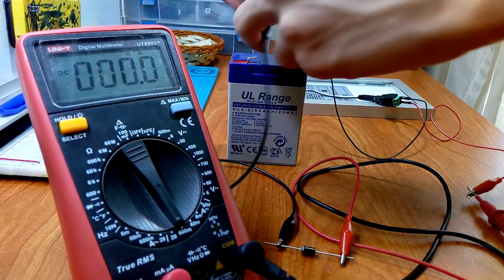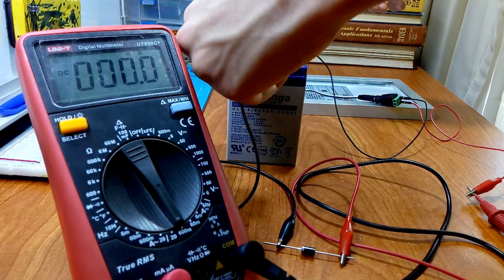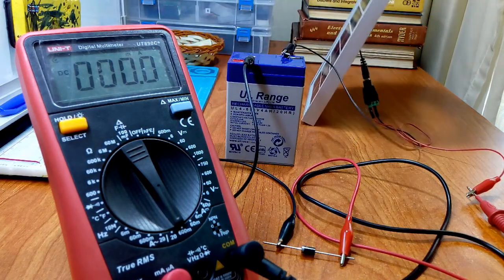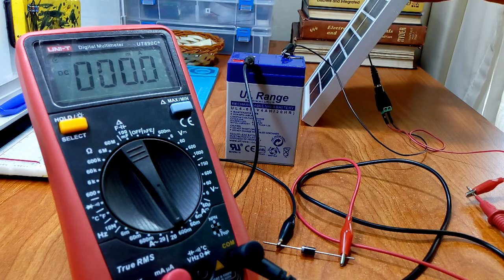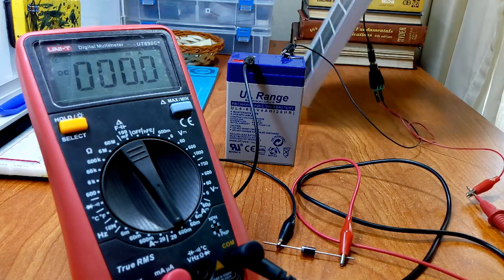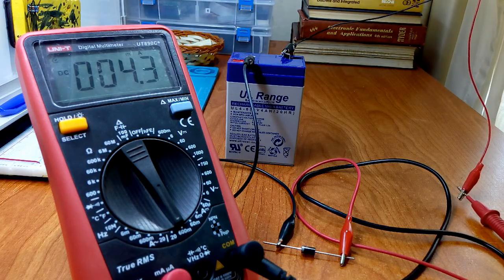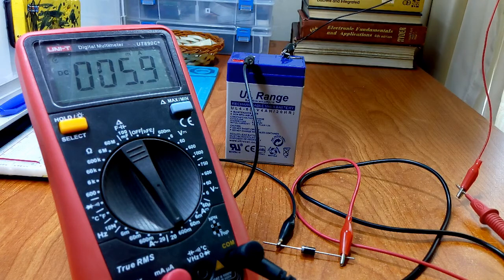I will not talk about the types of diodes you could use and the best one, because the video would be too long and too boring, but I will just say in short that it actually works. So now there is no negative current, there is no current being drawn from the battery, only current forwarded directly into the battery from the solar cell.